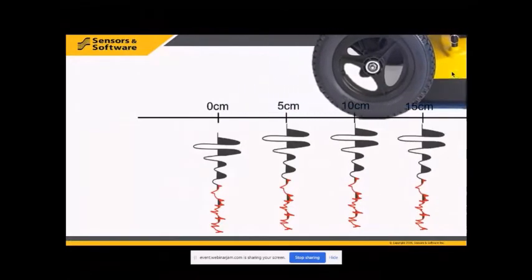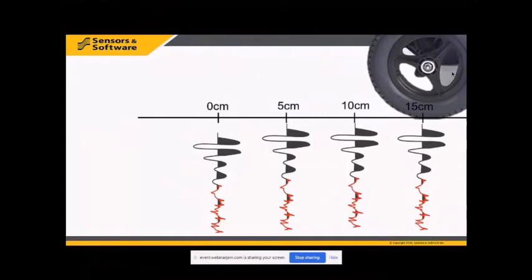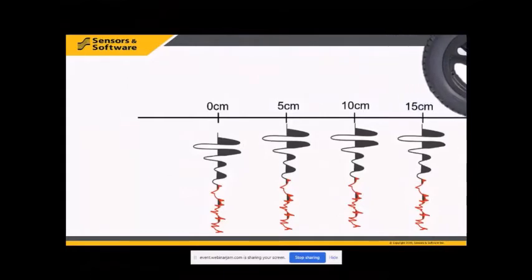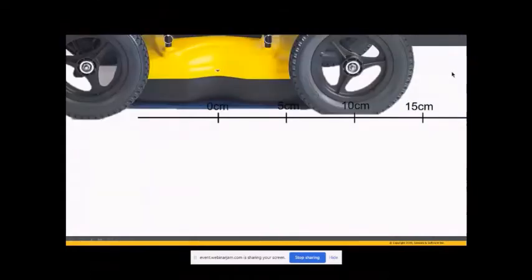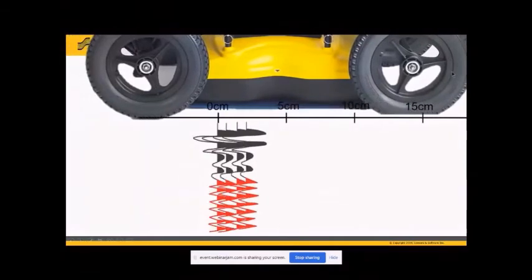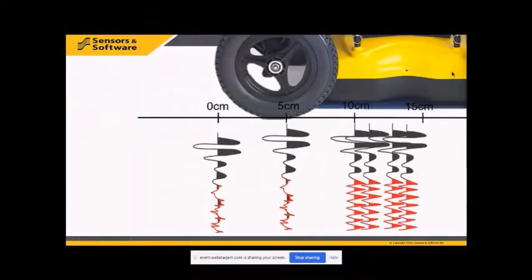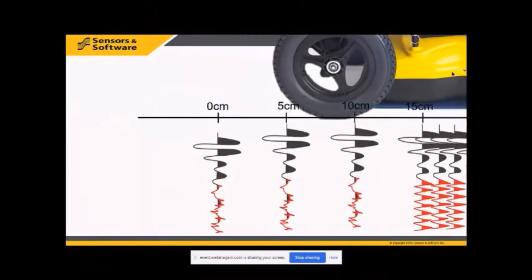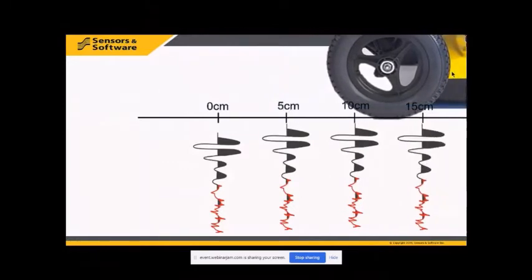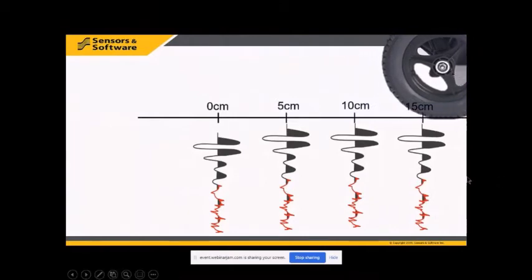Notice that the average trace of the 4 traces collected has less noise, again shown as red signal in this example. Since there are GPR signals buried below the noise, this means that if we can decrease the noise, we can see those weaker, deeper, real GPR reflectors.